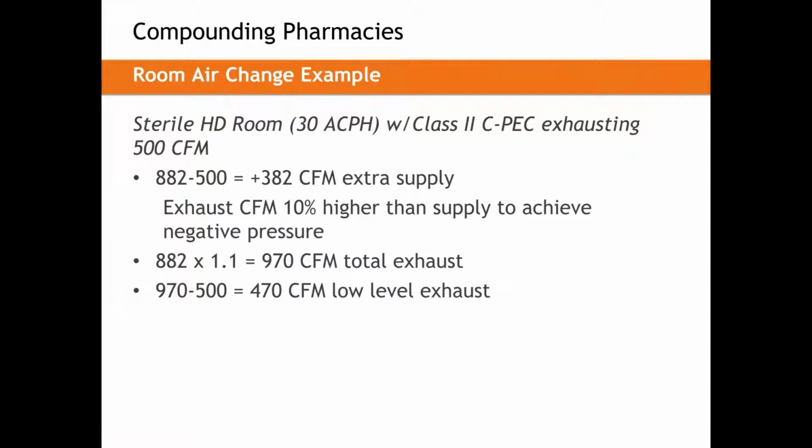That number and the pressure created by those two relationships needs to be finely tuned and balanced on site. As design engineers, we like to say it must be 10%, it must be 82 CFM. That must have flexibility to be changed on site. It's up to the balancing and commissioning team to make that right. As engineers, we cannot hold too tightly to that number because we can't guarantee in the design phase what the construction of that space will be.